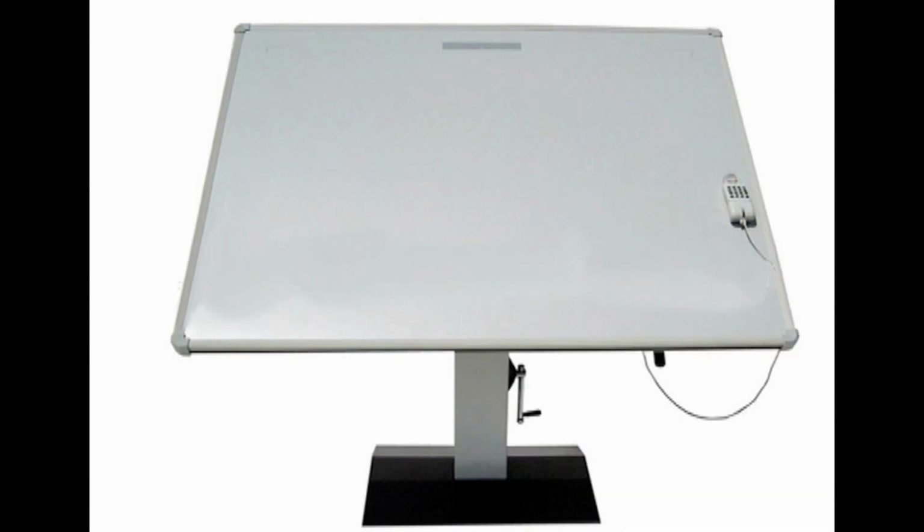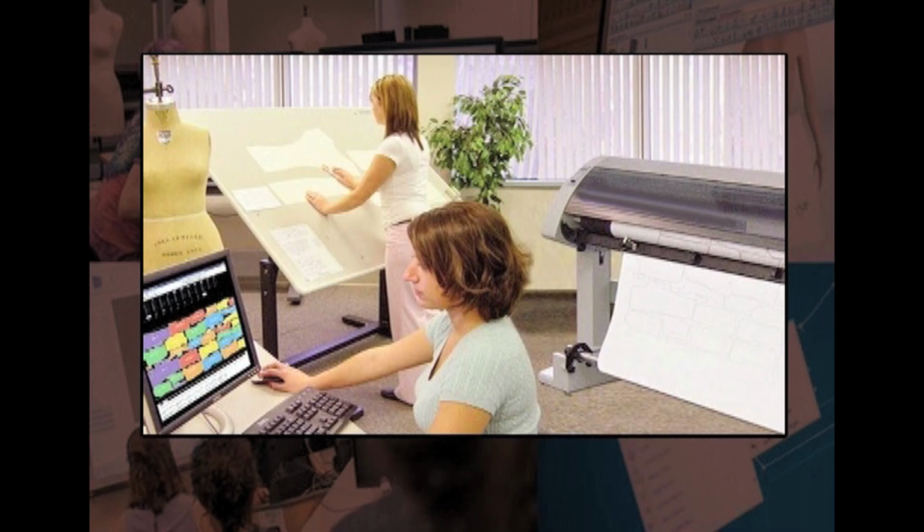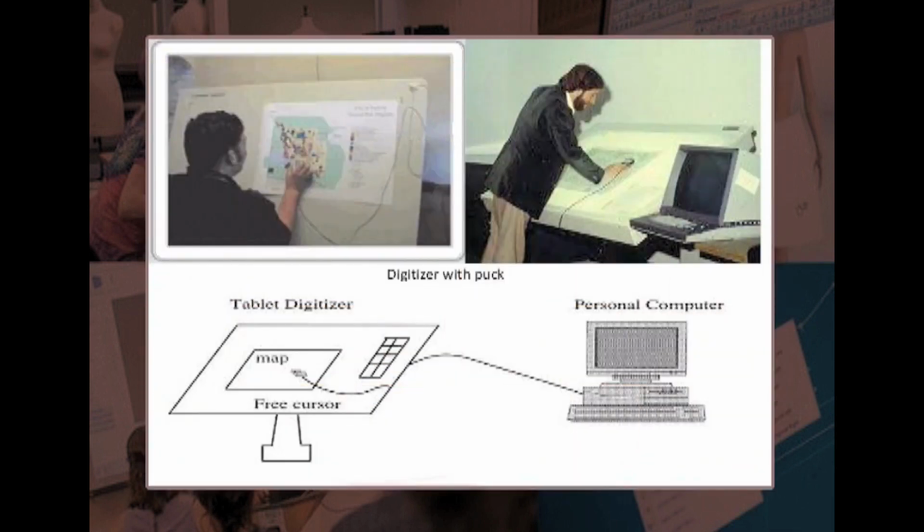Digitizers are also available in different sizes. The 12 by 12 inches and 12 by 17 inches tablets are considered working digitizers. Digitizers are also available up to a maximum of 40 inches by 60 inches, which are highly expensive but provide utmost flexibility for working. They are also useful for entering patterns and illustrations. Larger items may, however, have to be digitized in sections.